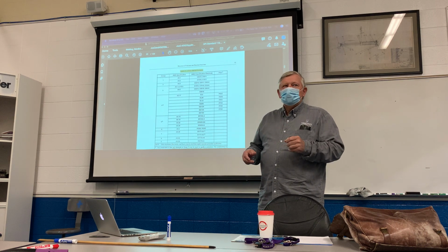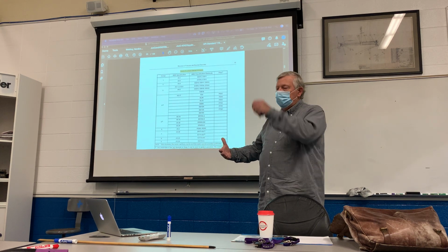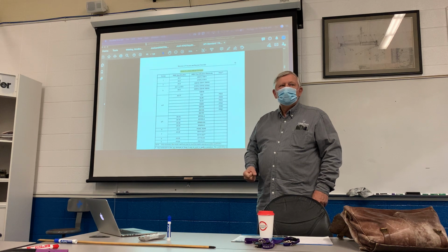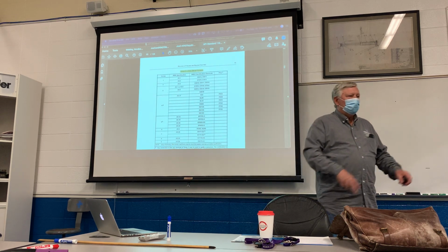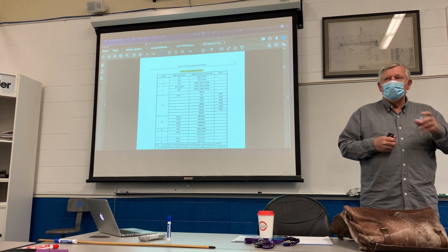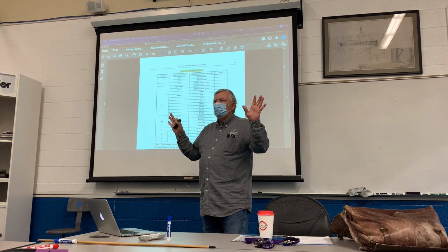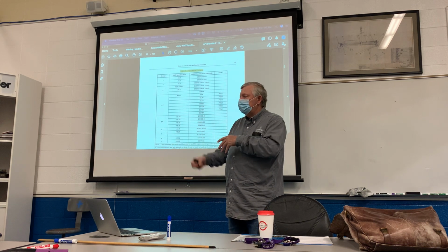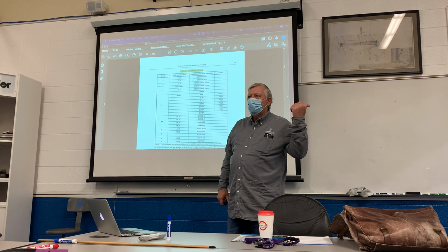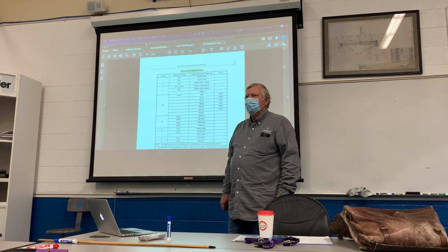So a lot of these times they'll say, well, the procedure says 250 plus or minus 50. So as soon as they're heating that thing up, and as soon as they get a 200 reading on a temperature crayon over the gun, they'll shut down that preheat operation, and they'll go over and they'll make a tamale, and they'll eat a couple bites of the tamale and have a cup of coffee, and then they'll go back and they'll start welding. And you'll say, whoa, wait a minute. You're supposed to preheat that. And he said, I did preheat it. But it's not 200 anymore, because you walked away and you ate a tamale and you came back, and it's probably now down to 150. Well, I preheated it to 200.